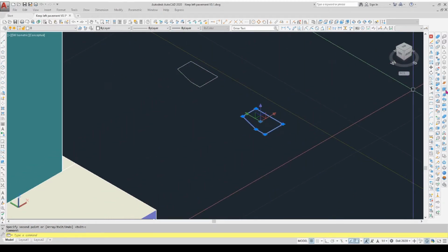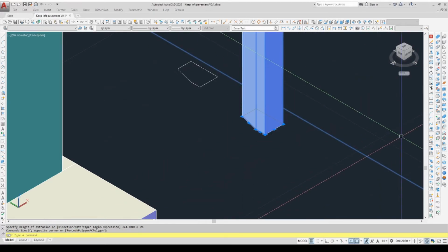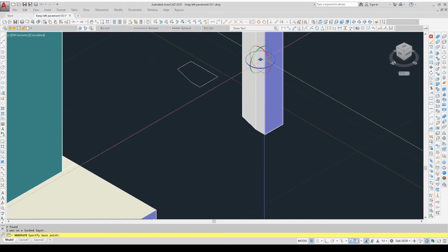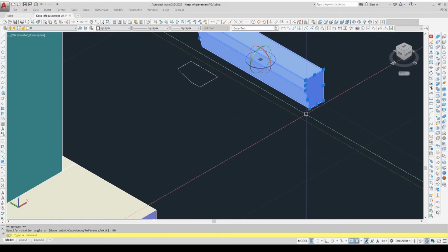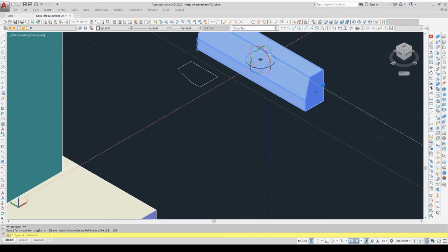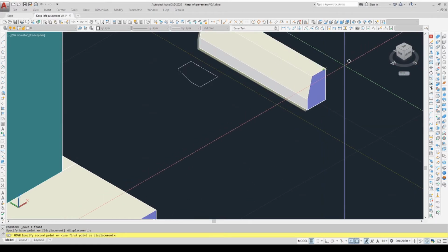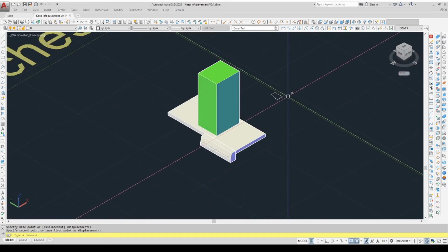So just quickly extrude that to 24 inches again, grab it and rotate it on the red one again by a factor of 90 degrees. Oh, wrong 90, so that's 180 to make it the other way around. And I can now move it back to where I had it before, and seconds later we're back in a format where we can keep on working.